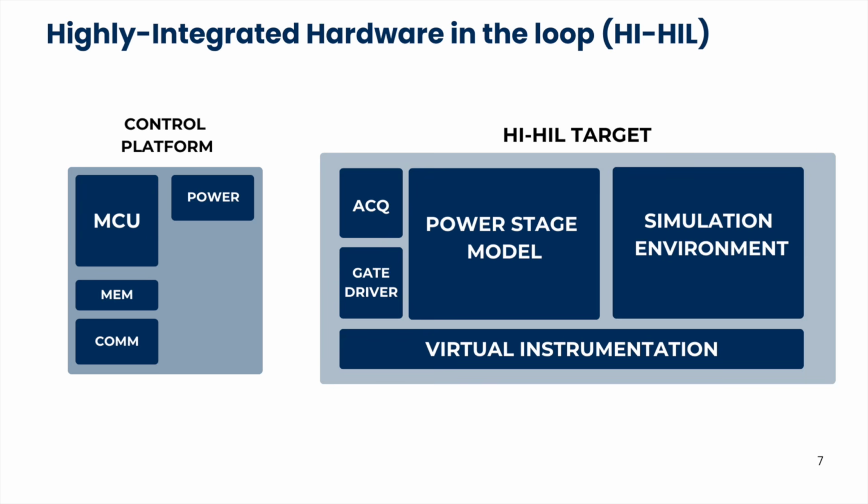These targets are usually based on FPGAs. So if we have an FPGA and we have the power stage, the model of the power stage, and also all the scenarios, all the simulation environment, we can integrate inside the virtual instrumentation. Virtual instrumentation is just we are going to take the different measurements from the model, and then we are going to need a way to extract that measurement from the FPGA.